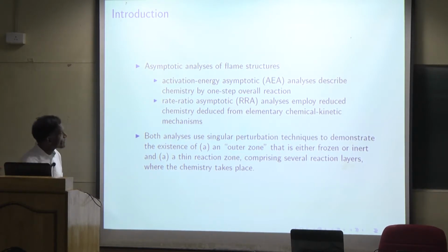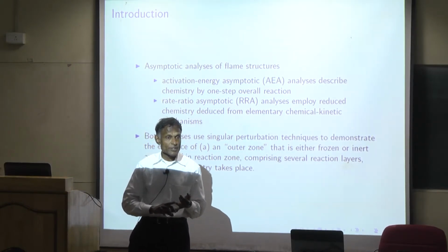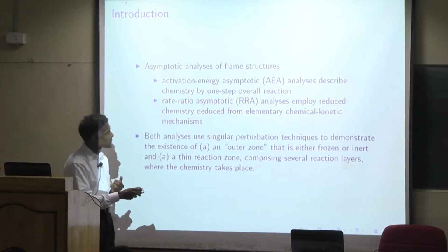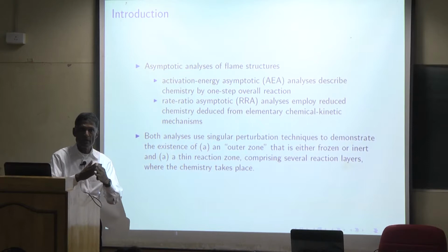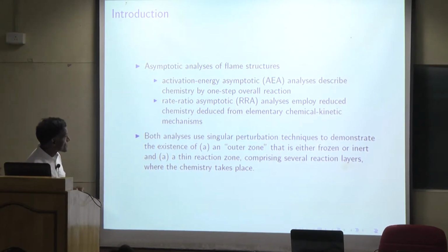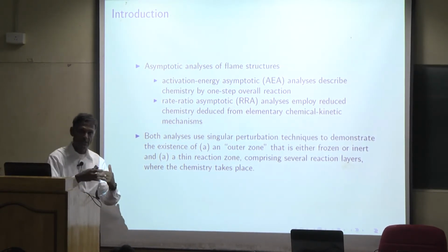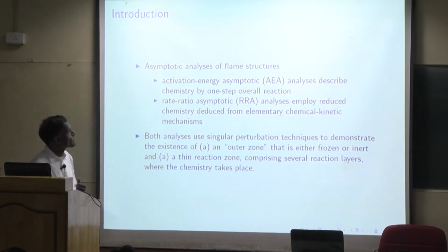Now, what is common in both? Both use singular perturbation techniques. I talked to you about regular perturbation analysis and singular perturbation analysis when I talked about fluid mechanics. The problem is singular in that you lose the ability to satisfy the boundary condition, so to satisfy it you have to force certain terms in. Both will have an outer solution and an inner solution, and then you have to do matching. So this is basically classical boundary layer theory as applied to reacting flow.